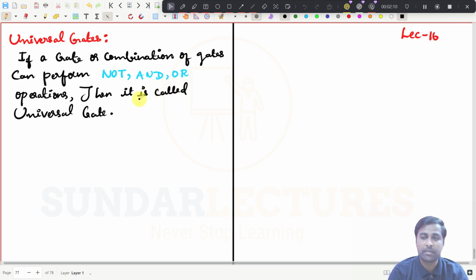Can you understand? The concept behind this is that these three operations, NOT, AND and then OR, are the whole set of operations that can be performed in Boolean expressions. If you take any Boolean expression, you can implement it with these three operations. And if a gate can do these three operations, or a combination of gates can do these three operations, then obviously we will call that a universal combination.